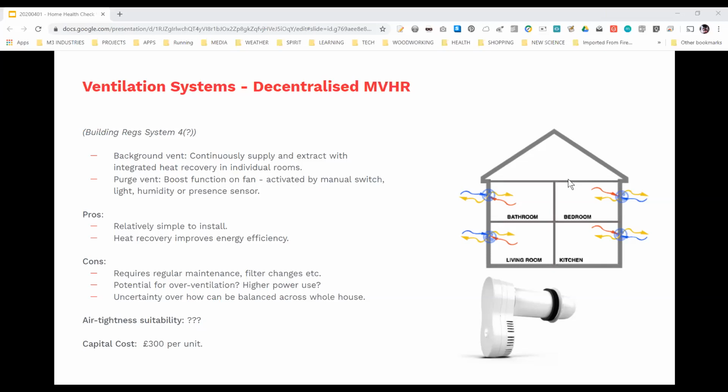And my customers report that that produces a very livable air quality space and no problems with ventilation. In terms of retrofitting into an existing window, it is a matter of cutting a slot or a series of drilled holes and then putting the vent on the inside and the cowl on the outside, and that takes me about 30 minutes.